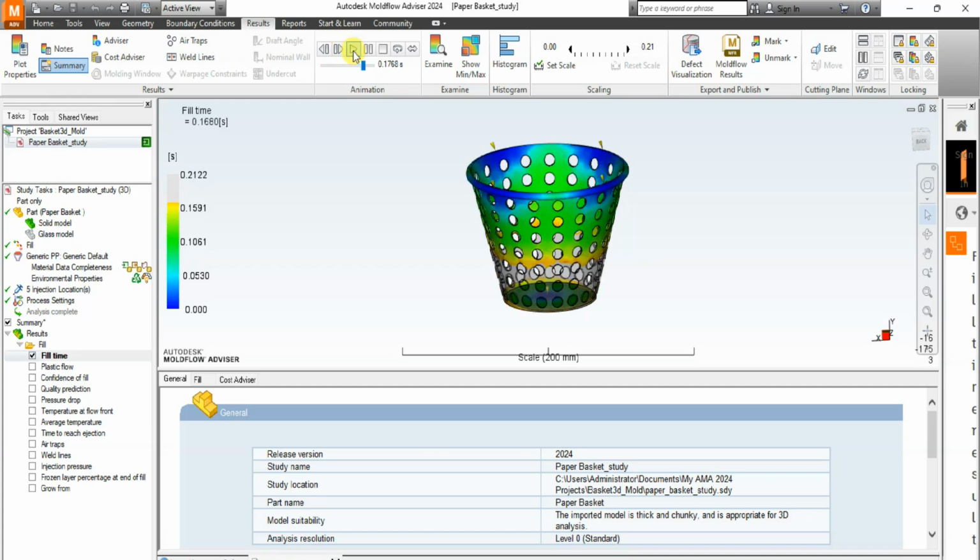That is for short shots. Another thing you should understand under the short shot is that in the fill time result, a short shot will appear as translucent. So you should check the ends of the flow for any translucent areas. Those translucent areas are like gray areas for models analyzed. For models analyzed with 3D analysis technology, you should also take note of the unfilled cavity, to see if there are any unfilled sections in the interior parts.